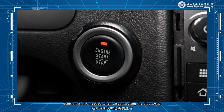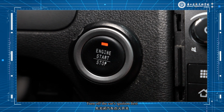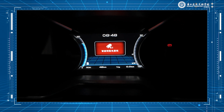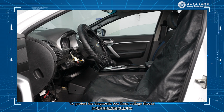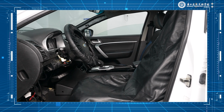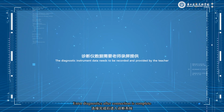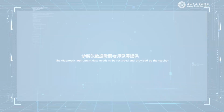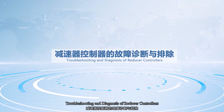Caution is also needed when disconnecting the diagnostic. Turn off the car's ignition first, then disconnect the cable, to protect the diagnostic box from voltage shocks. Enter diagnostics after the connection is complete. Read the relevant data streams for troubleshooting and diagnosis of the reducer controller.